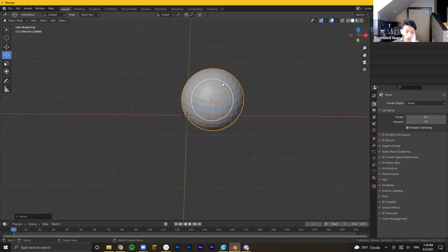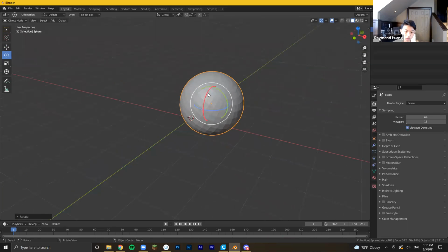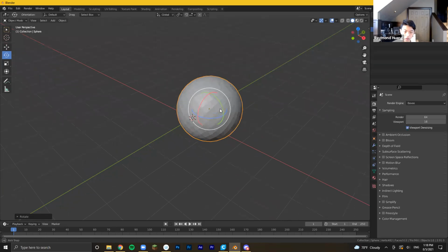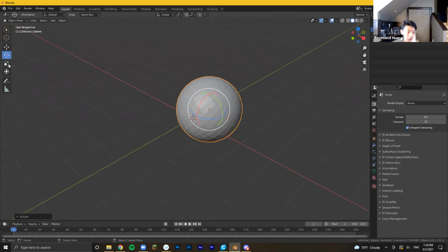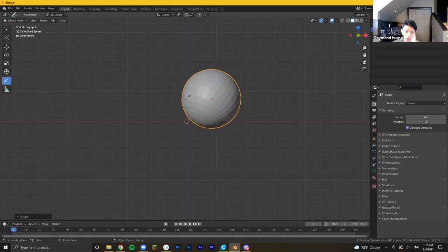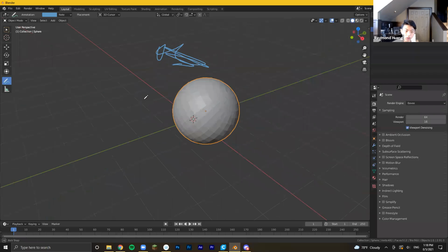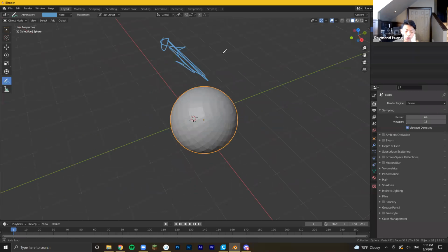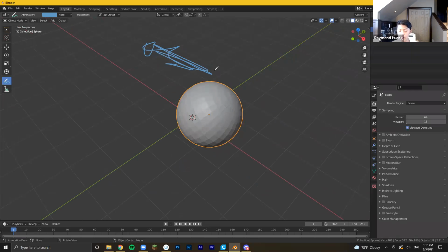This is the rotating gimmick, so you can rotate it on the y, x, z, that sort of stuff. There are also annotate tools. You can sketch your ideas right onto the scene, which is good for sketching out your ideas before you actually start modeling. Then you can trace your sketch with actual 3D geometry, which is pretty cool.